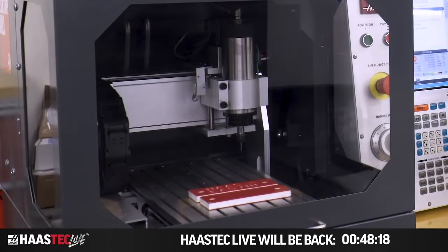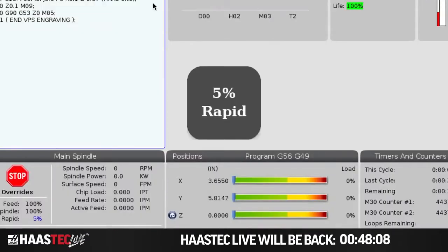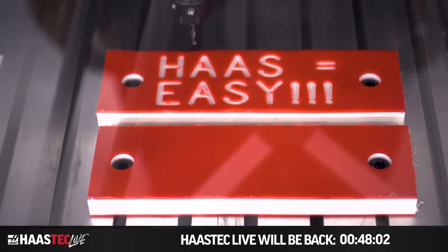But since we already have the tool in the spindle, per the message on the screen, I'm going to push the letter K to continue. And now I'm going to change the rapid override down a little slower. Now that we're moving in the right direction, it looks like, speed it up a little bit.